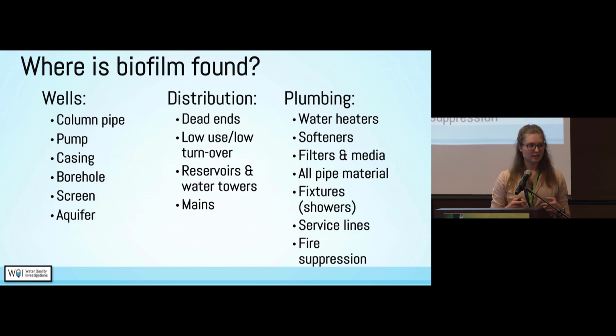Softeners, filters, any sort of media is something where we have really seen a lot of biofilm growth. The reason is that there's a lot of surface area in there for biofilm to grow onto, and also it's going to get backwashed and regenerated, but that's not always strong enough to remove biofilm that's growing in that.